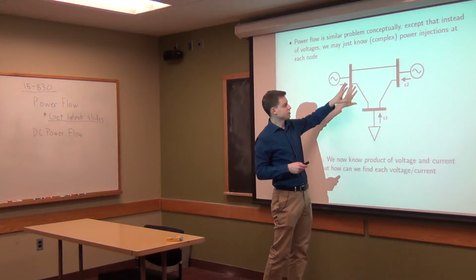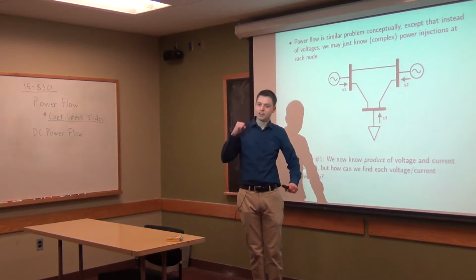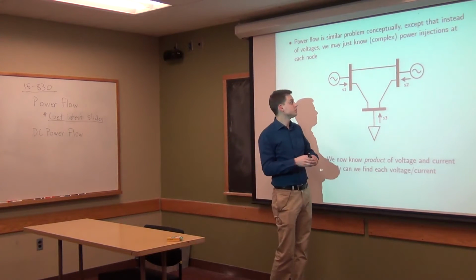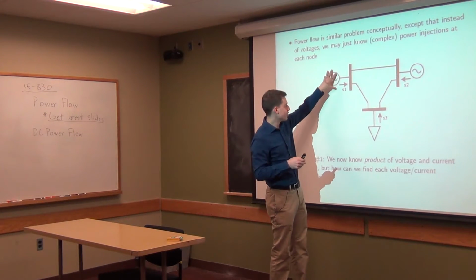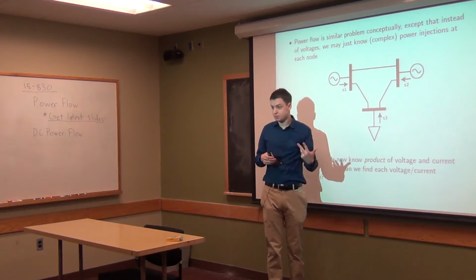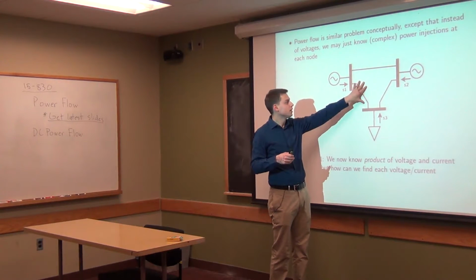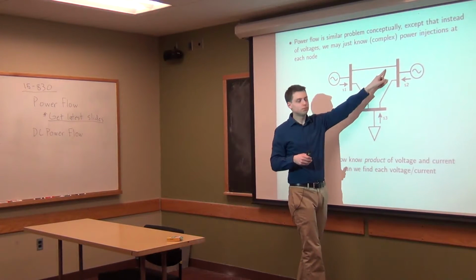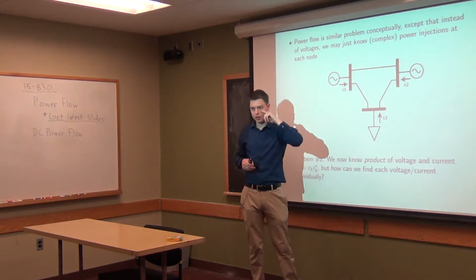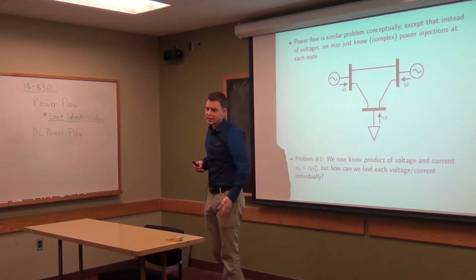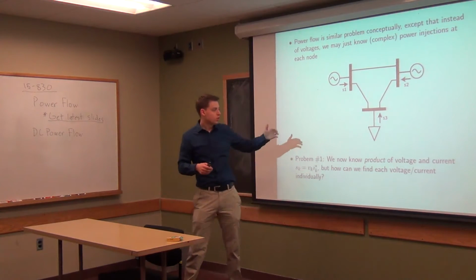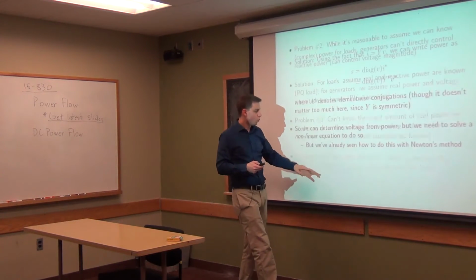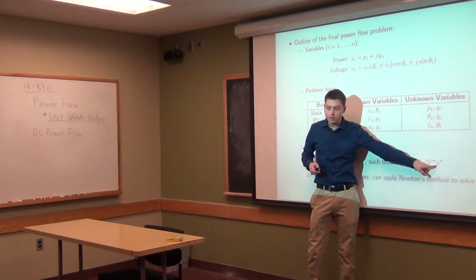You have buses that are essentially just nodes in that network. They're connected, and they assume you have 0 resistance between those. So if you had a load and a generator on one, you would assume there was 0 resistance and 0 impedance between them. And then if you assume a pretty simple model for these transmission lines, it's actually quite easy to write down what this Y matrix here is, what the admittance matrix is.